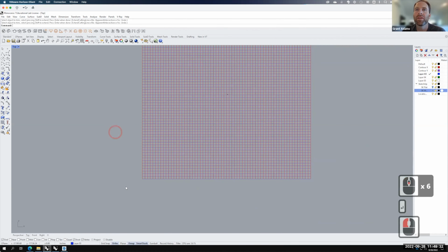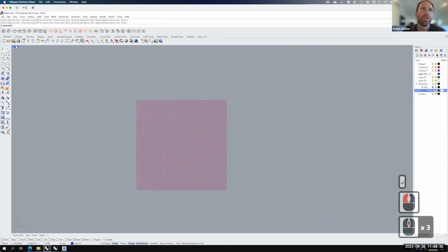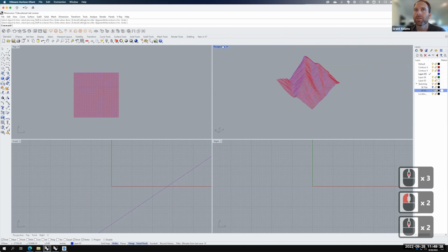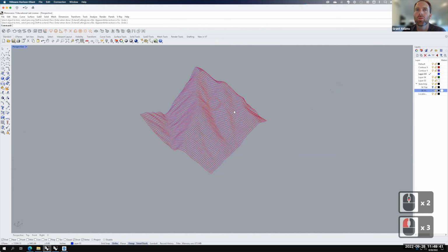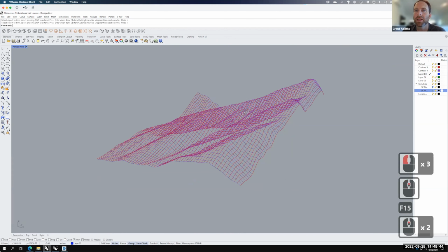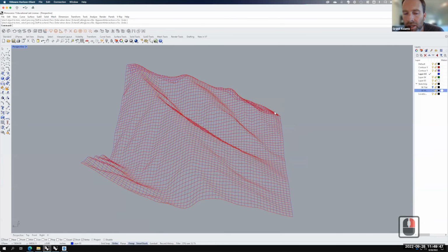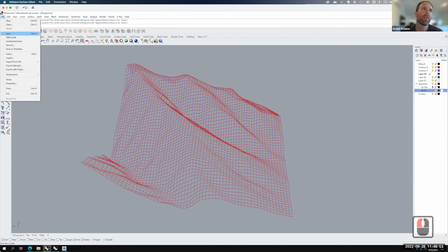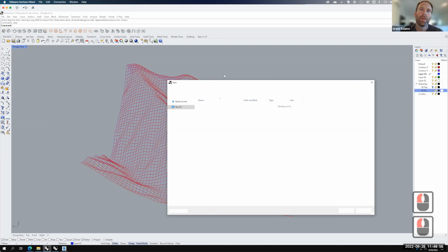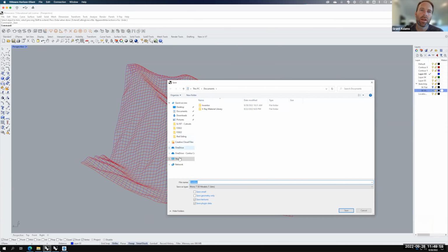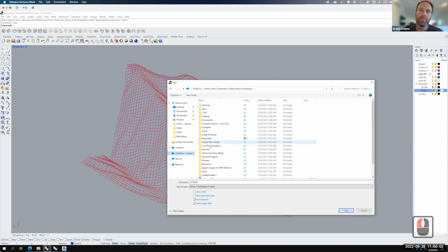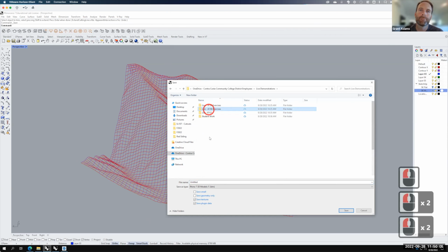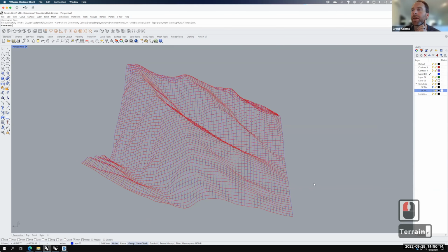So based on what we've previously done, you probably know where I'm going with this. This is where a curved network goes in to place. So we're going to use that curved network or a network surface to create a brand new surface out of those intersecting contour lines. Now, before we do this, this does have an opportunity to crash. So we're going to save our work. So I'm going to go to File and then Save. And this is important. And so let me put it in my folder for today. And I'll choose Save. Perfect.